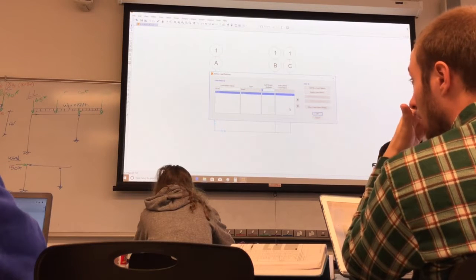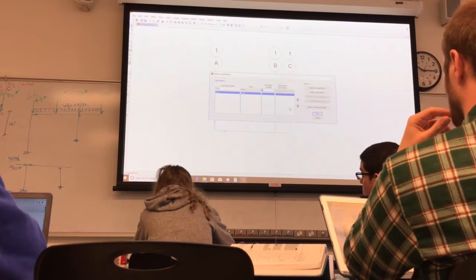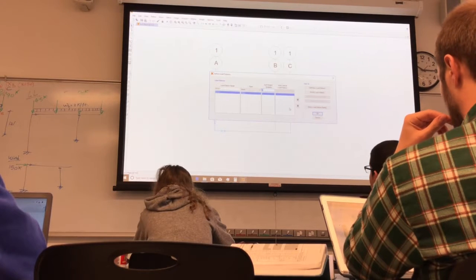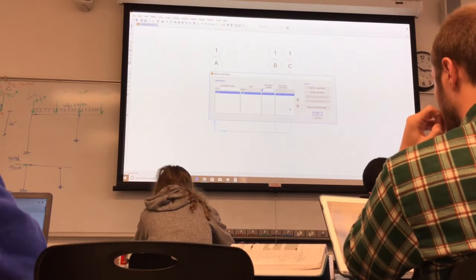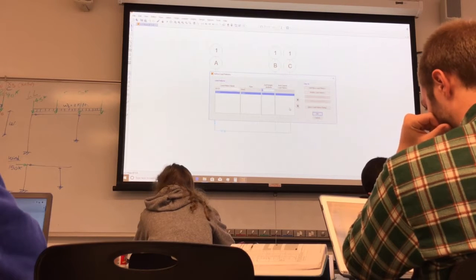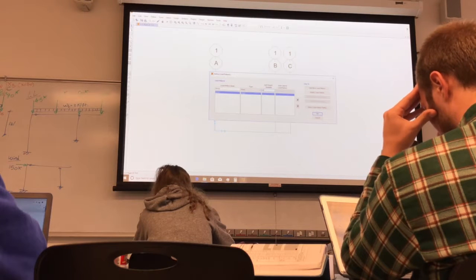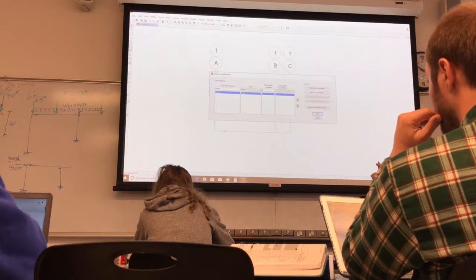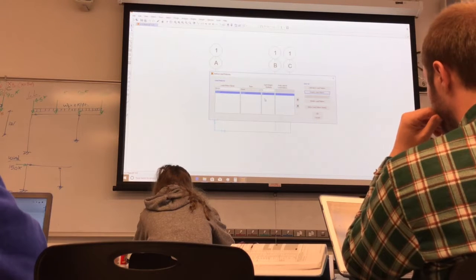We mentioned in the example already that the self-weight is included already in this 3 kip-foot. So we don't have to account for that twice. So we put the self-weight multiplier of 0. And then we click modify, you see a 0 here. That's what we want to do.